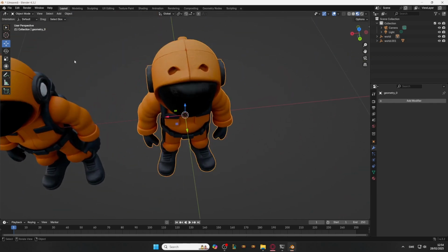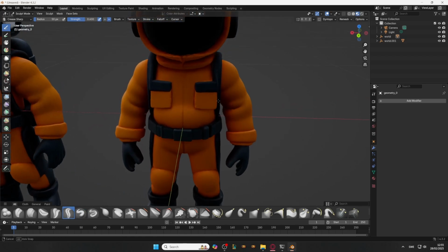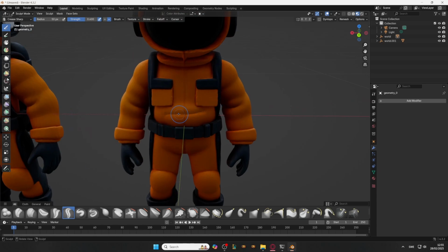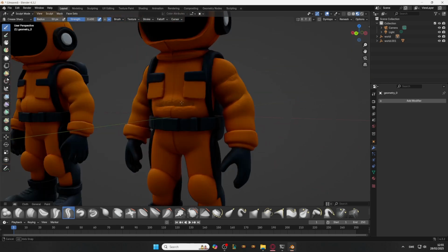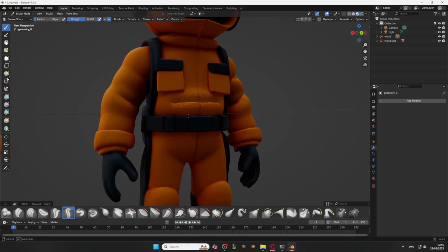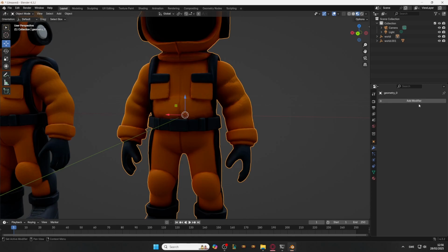So let's go over to the sculpt mode. As you can see, with the texture it looks phenomenal, but the texture hides a lot of defects, obviously. Okay, so let's try the sculpt. I'm just going to sculpt a crease, and it looks decent enough. For 3D printing, this is actually okay, and you don't need to simplify the model or remesh the model anymore. But if this is going to be used in a game and you want to add some detail, for example, a broken stomach or whatever, I'm using the shift button to smooth it here. You can see some breakage.